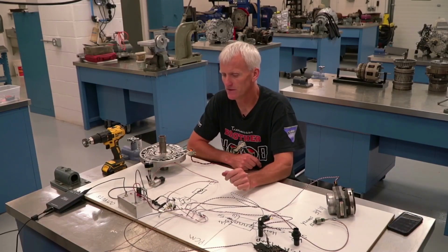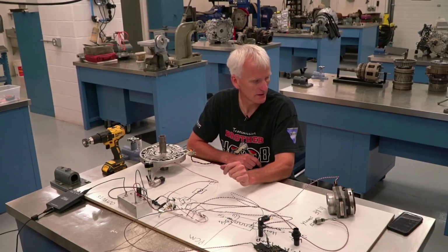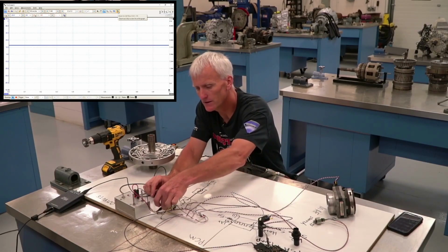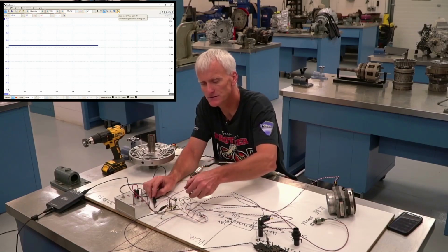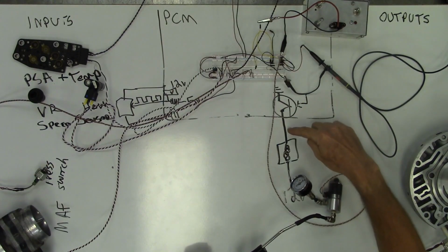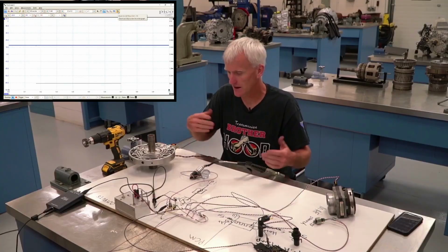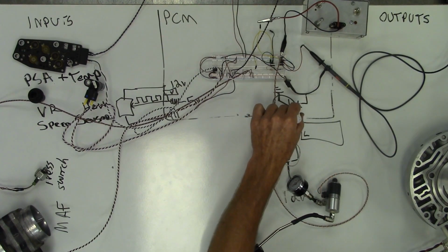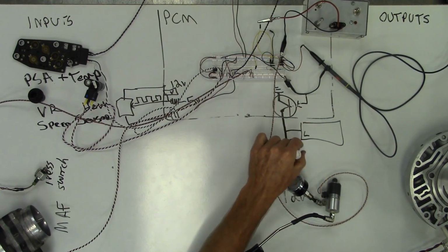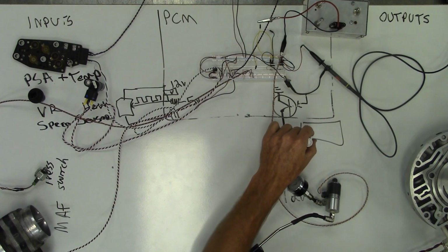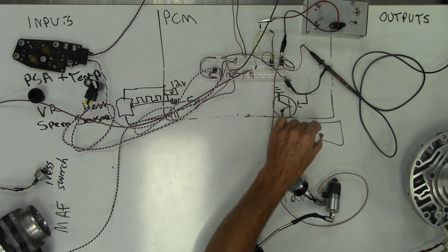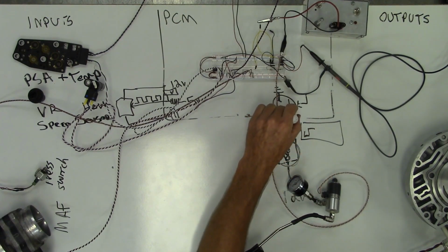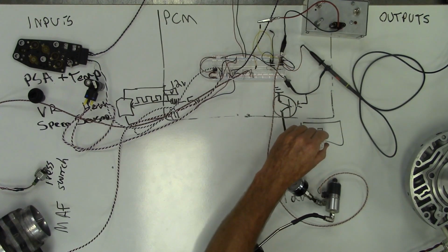They'll operate these things at a fairly high frequency, so you wouldn't normally hear that. I went ahead and put the scope on there, so I've got the scope grounded out, and it's connected into the ground side of the transistor. So I'm checking the voltage right here so we can see how it's controlling the solenoid. When the transistor is applied and it provides a ground, I drop all my voltage across it, and I see the voltage drop low. And when the voltage goes high, the transistor opened up the circuit, and voltage went up. And then when the transistor provides the ground, it goes back down, and I get the square wave.